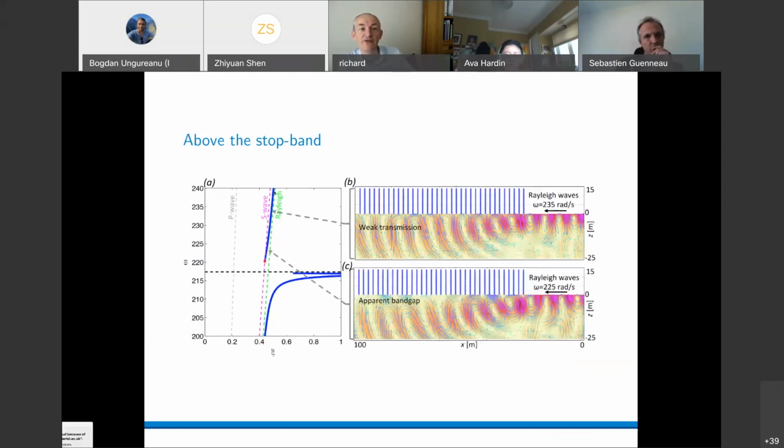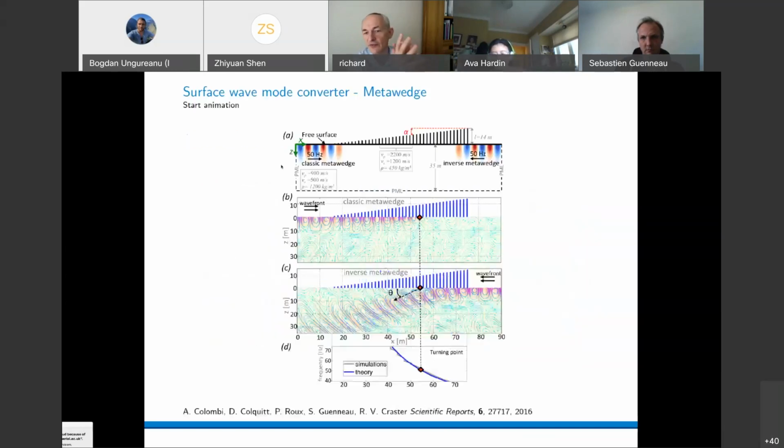As we go down in frequency, we find that our wave changes its character from being a Rayleigh wave locked primarily to the surface into appearing more like a shear wave as it begins to propagate much deeper below the array. Those are interesting features, but having an array all the same height is not enormously useful because of this very, very narrow band gap.